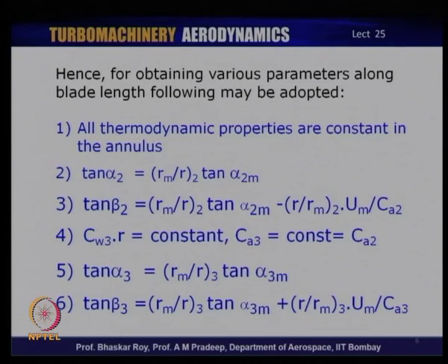The free vortex design essentially gives us thermodynamic properties that are constant from root to tip, which means they are constant in the annulus through which the flow is passing in the axial flow turbine. Remember, it is an annular flow, and hence in its annular flow passage, we are now invoking a law which promotes constancy over the entire annulus.